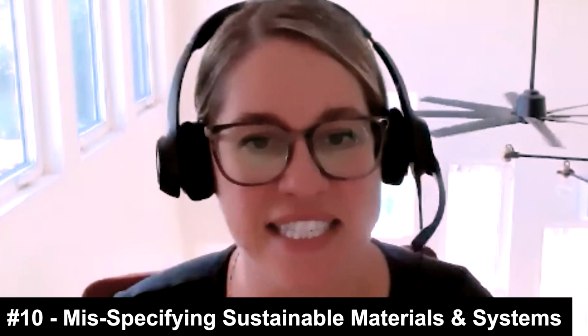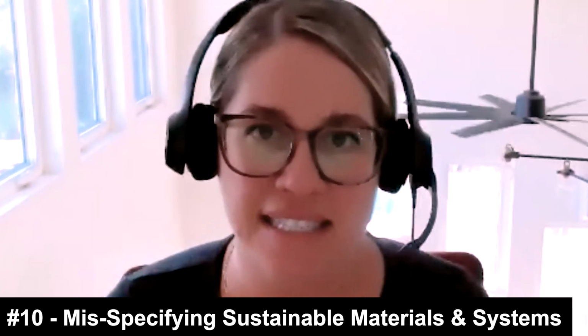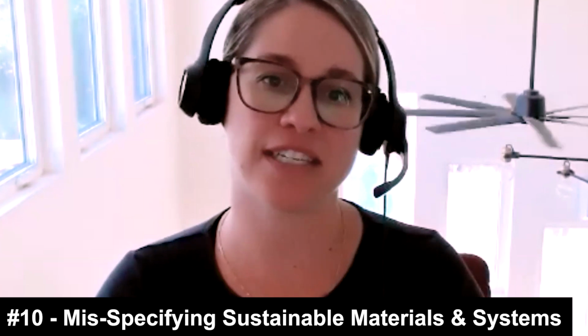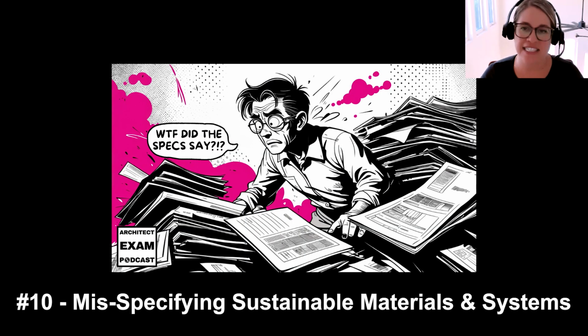Okay, everyone, we've made it to mistake number 10, which is misspecifying sustainable materials and systems. What do I mean by this? This is when we're working on projects that have specific requirements about sustainability, whether it's a system or the actual sustainable materials of a project. There's a lot of increased focus on sustainable design and green building certifications in a lot of projects currently, and this mistake is becoming more and more common. Specifications for sustainable materials require special attention to details like recycled content, VOC limits, and documentation requirements.